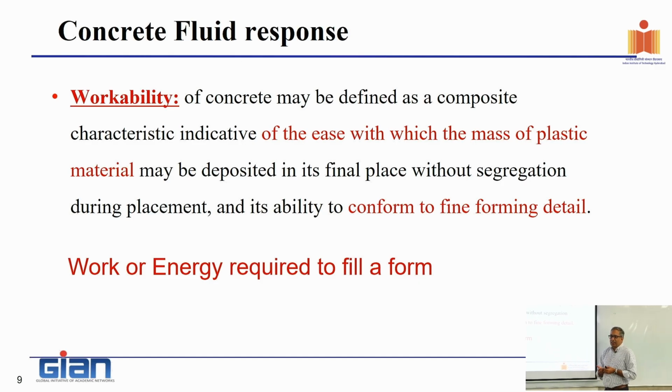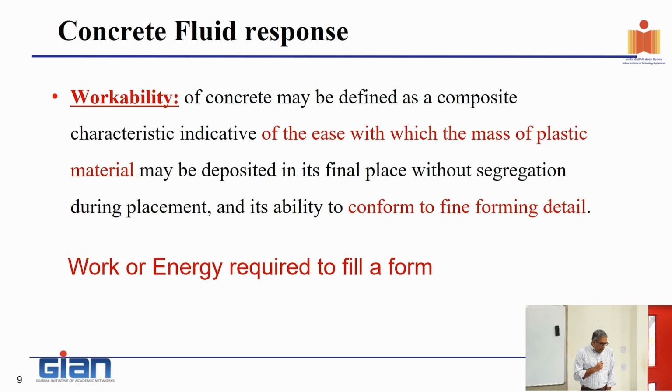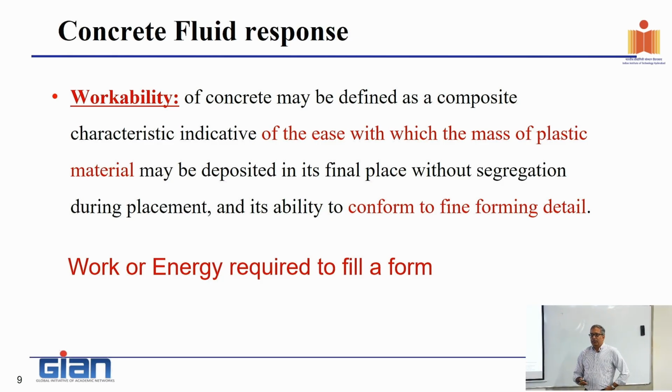Okay, when we say concrete is plastic, at some level we expect it to be a fluid when it is forced to flow, and that when it is deposited in its final position, it is able to conform to the final fine forming detail. What is implied by that? Suppose I put concrete in a rectangular box. I expect concrete to fill every corner of that box. It has to flow, fill that. That is how I define my workability. If it doesn't fill by itself, well, if I force it, then it should fill.